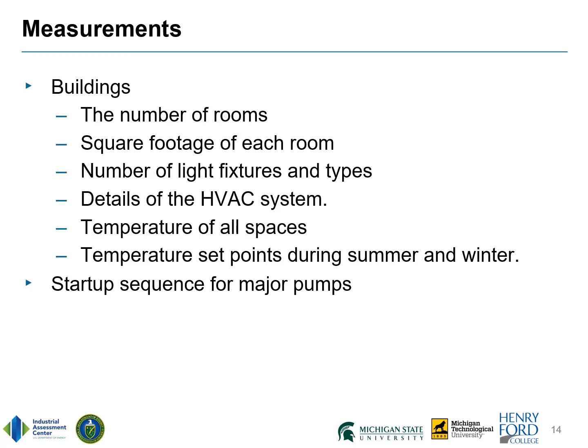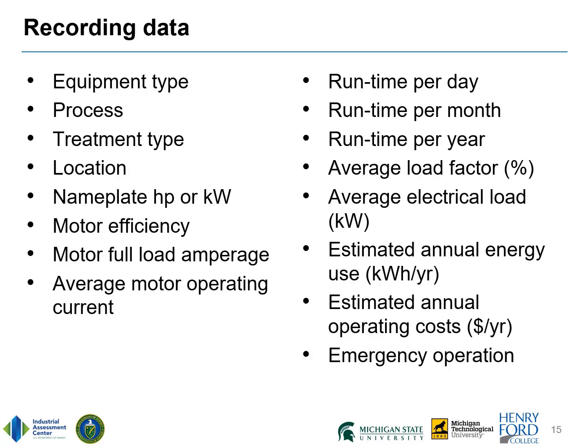Recording the startup sequence provides important data to understand startup loads that have a large impact on electricity demand charges. If the wastewater treatment plant has a filtration system, then be sure to obtain information on the backwash pumps for the filters. As previously mentioned, before the site visit, you should review the as-built facility drawings to determine what equipment is at the plant and generate a list of items to be tested. Construct a spreadsheet to track all of the data you wish to collect.